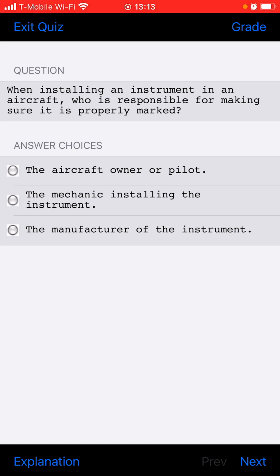If an aircraft with retractable landing gear has only a green light to indicate the gear down and locked, how will the switches be connected, in series or in parallel? The switches are connected in series.